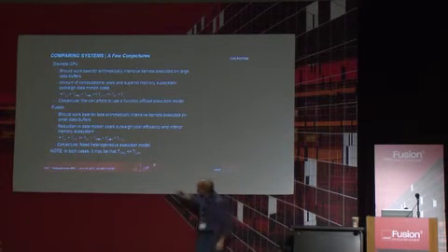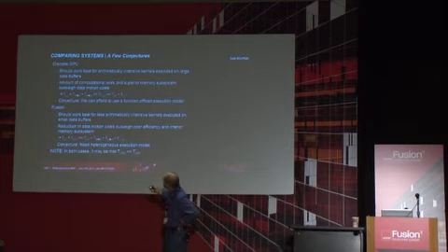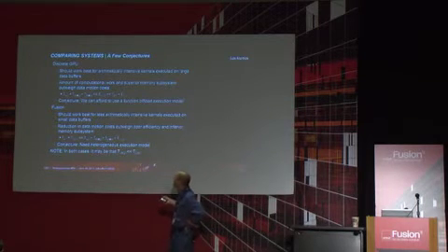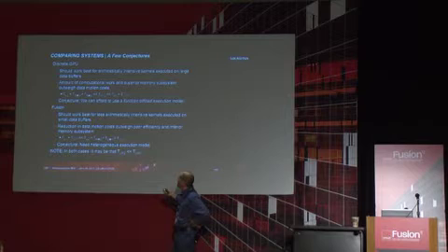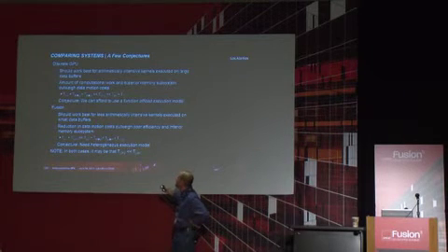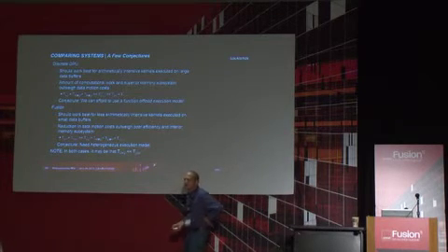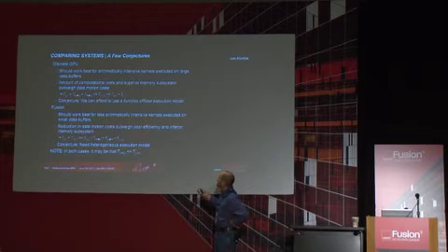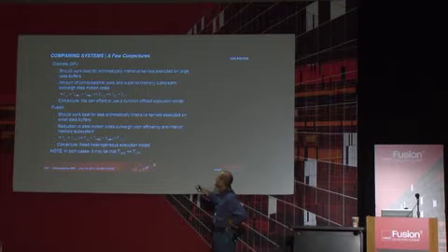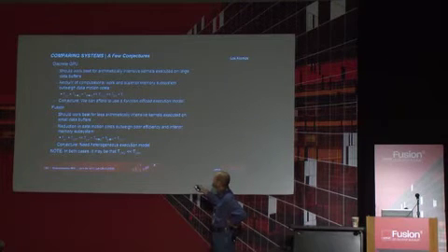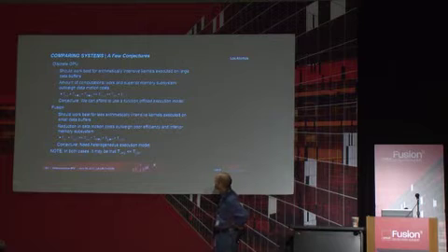So I guess this is not too good to see, but this is my cost to enqueue, which potentially could be higher because the enqueuing of the kernel has to go across the PCIe bus. I have host-to-device and device-back-to-host cost. Now, if these are much less in total time than the time it takes for me to compute on that device, I'm going to win. And potentially, that time is much less than what I would have on the Fusion part. So this is the Fusion enqueue and the Fusion computation.